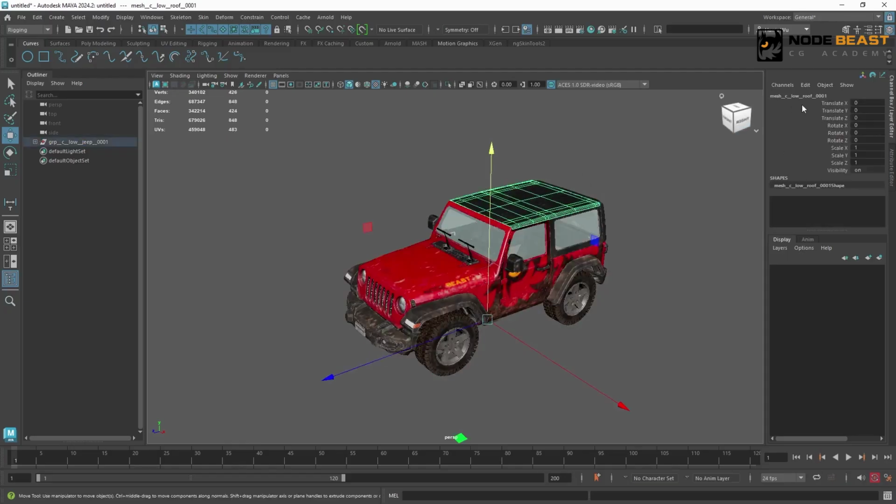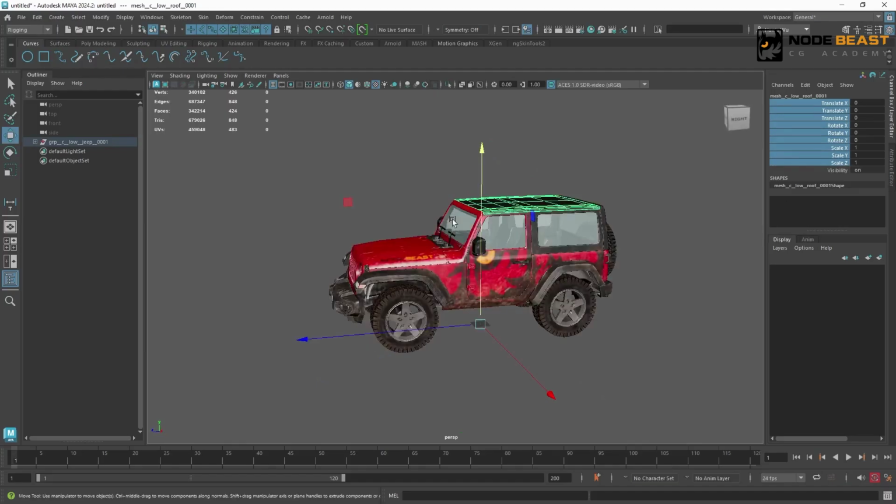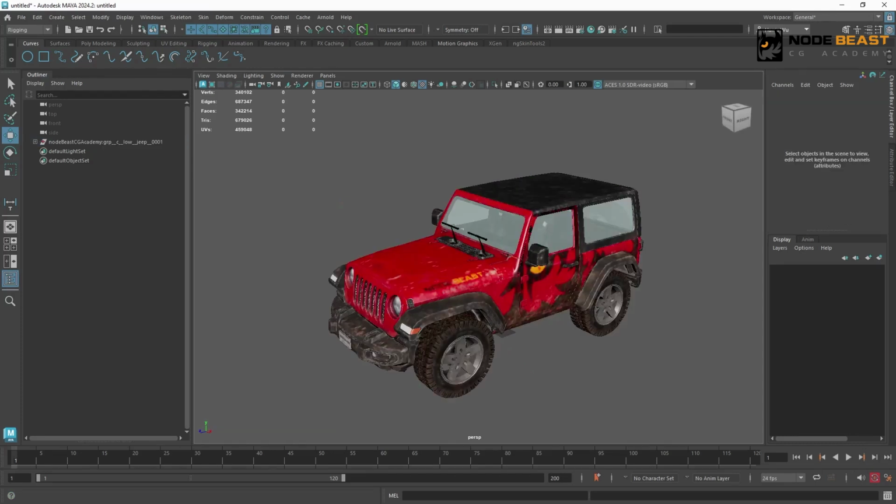Then, next are some steps we learn in modeling that I believe we are all very familiar with. For every model itself, we must freeze transformations. Ensure its translation, rotation, and scale are all at default values. Then, we must delete history. Then, on model parts, their pivot points must all be at the world origin. Next, we need to check the naming.